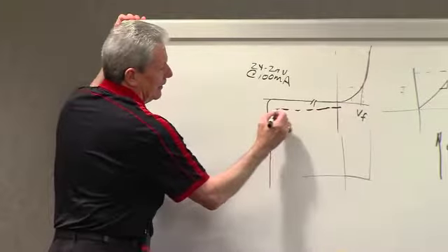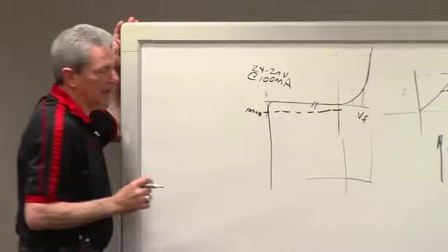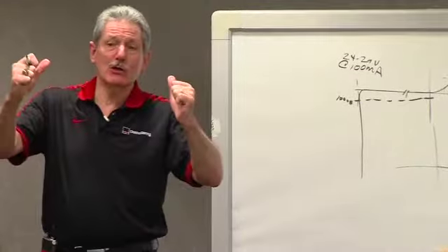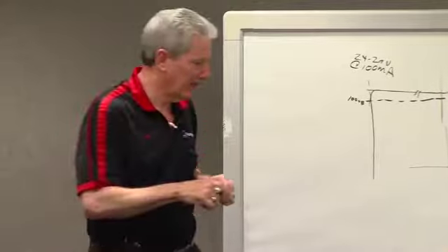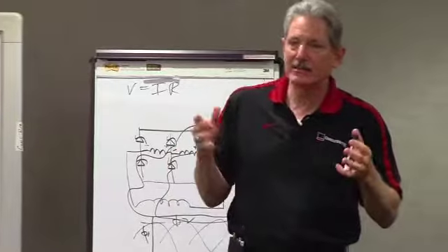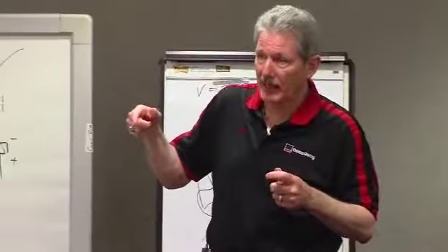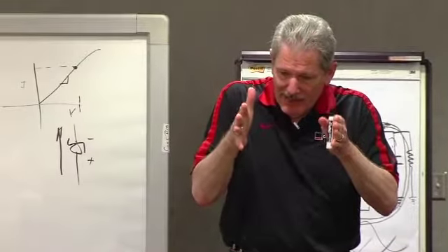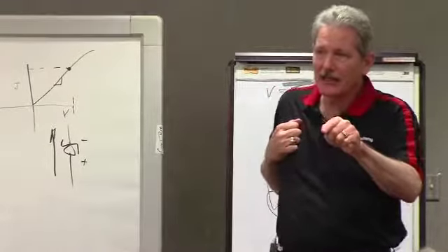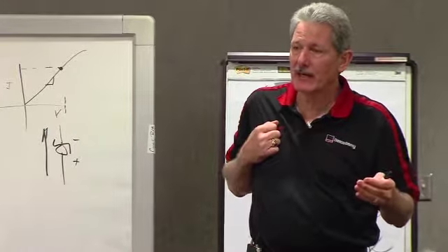So here we've got 100 milliamps, and this is 24 to 29. So at that point, the diode flows current in the reverse direction, and here's why. The current in an inductor cannot change instantaneously. The current in an inductor, as an analog, the voltage on a capacitor, stays fixed. As soon as I take the current off of an inductor, the instant later, the same amount of current is flowing through that because it stores energy in the form of a magnetic field.